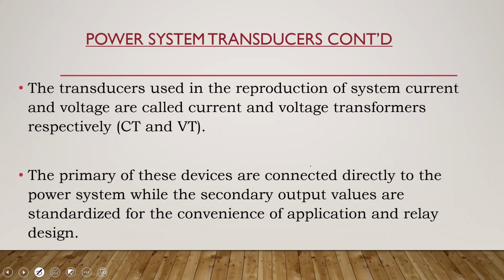You're required to get CTs that provide measurement, meaning it's going to be used to dictate how much money you pay the utility. You have to ensure that you get measuring CTs, which have very low error values. So you can't use a protection CT for measurement purposes.